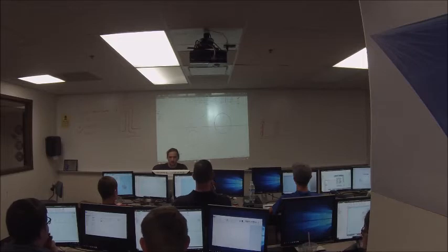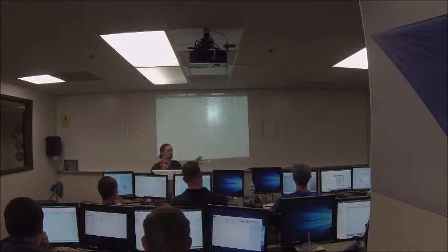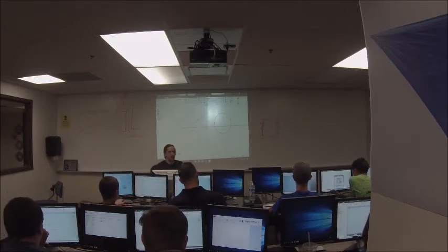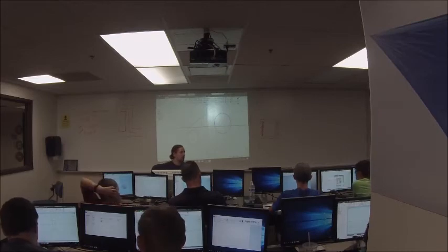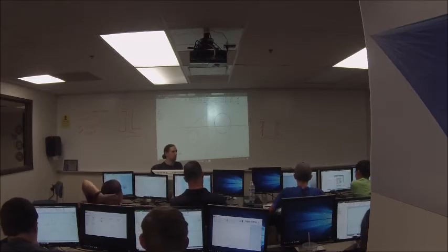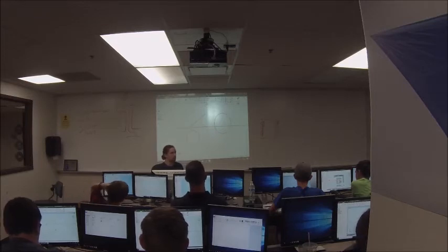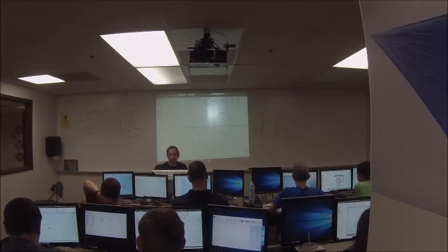This is a symmetric constraint, which basically, if you have a part that's symmetrical, it can help you make the part symmetrical so you don't have to repeat constraints on either side. I use it a lot. You don't have to use it. In a lot of cases, it's just more convenient to use it. I'm not really going to go into exactly how that works, but if you guys want to mess around with it, use it, be my guest. It's quite useful. And then this here is equals.